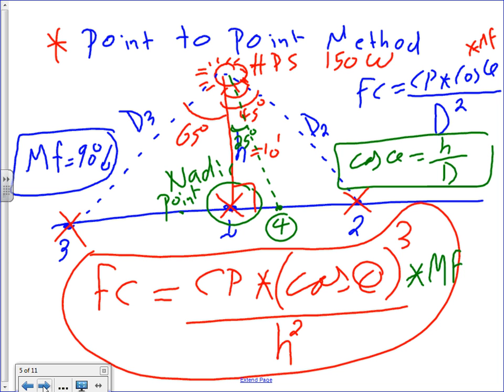Anybody rich man here? The rich man's work. This is called the point-to-point method. We're going to take an example. That's how Visual does it. When you draw the solid, and you did the calculation zone, and you put your fixtures, and you hit the button and start crunching, right? It was crunching numbers. That's exactly what Visual was doing, taking every foot by foot. I think it was 2 feet by 2 feet. The corner of every 2 by 2 square, taking it and doing a calculation right at that particular point to get you the brightest point, the dimmest point, and the average, and a couple of ratios. This is called the point-to-point method.